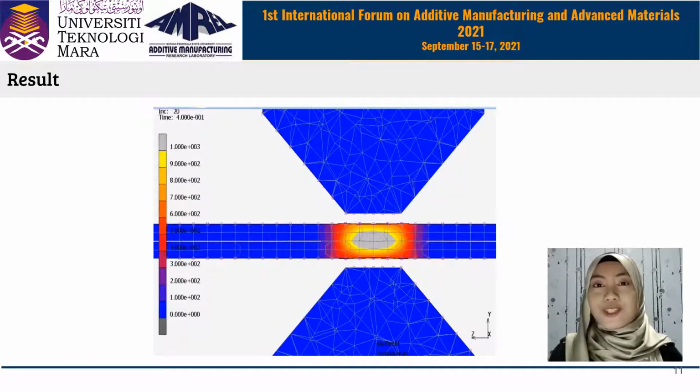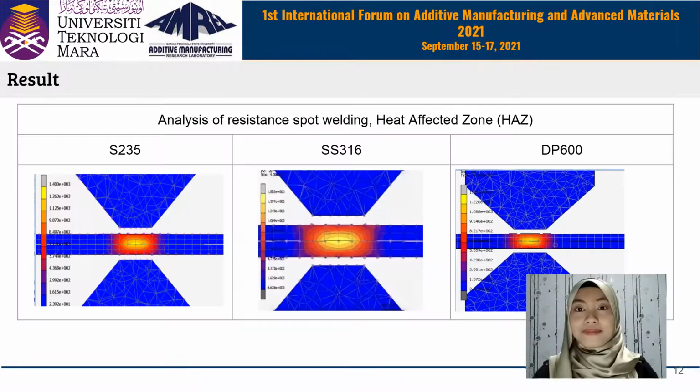This simulation showed the spot welding stage, which consists of 20 increments altogether. Following the completion of the simulation, the temperature study findings can be shown on the model. During resistance spot welding, a link between the surface temperature of a spot weld and the greatest temperature at the nugget center can be created. After that, the relationship can be calculated. It indicates that the weld bore the highest temperature in the weld center.